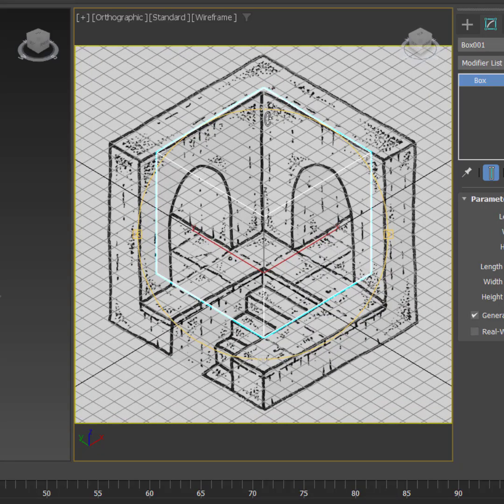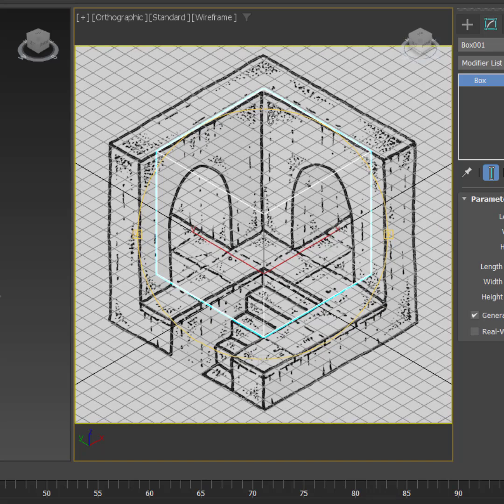So right now I'm aligning my object here onto the lines of the reference so that I can easily resize it later on, or I can easily position it later on in tracing. Next thing is I will right click to exit the view rotate. Again, the shortcut is Control R to bring out your view rotate handles, and then I will right click and exit. Next thing is I will resize this to a smaller size, or I will fit it onto the blocks there.